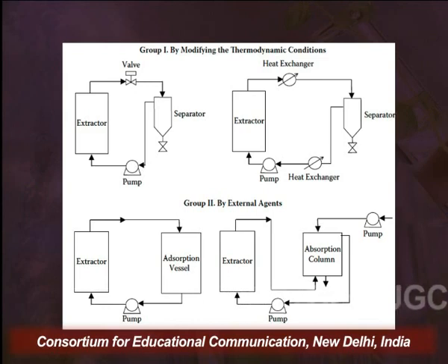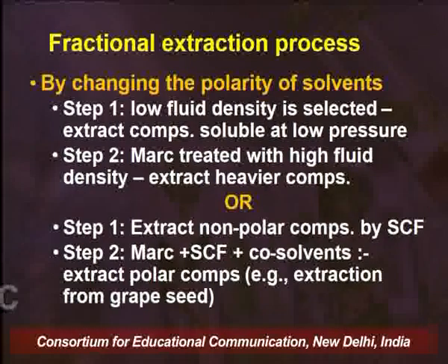Now, when that viscous liquid moves in a counter current direction to the extract, the constituents which are more soluble in that viscous liquid get absorbed into that particular liquid, and the gas, or the supercritical solvent, is separated. So these are the four major scenarios, that is how separation occurs once the extraction in supercritical fluid is over.